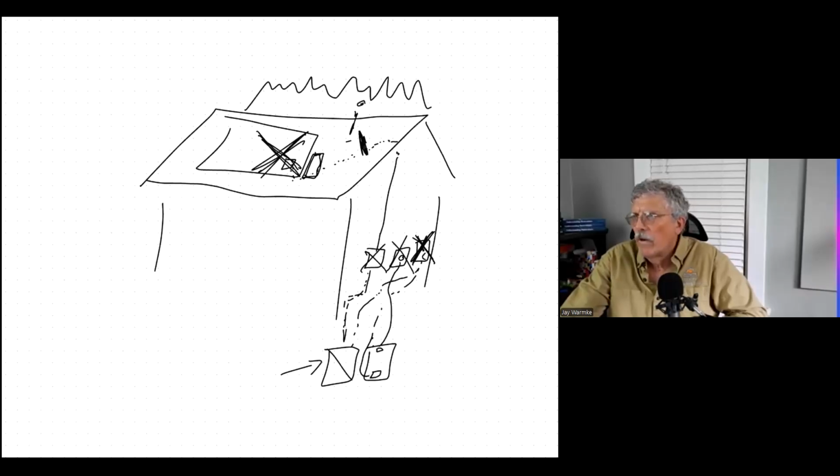They said like within 1 foot. So that was all fine. But that didn't work in residential. So then another company came up with the idea saying, how about instead of having one big inverter, why don't we make a bunch of little micro inverters and we'll attach one to each of the panels. And then when it loses sight of the grid, it's just going to shut off automatically at the array. And we'll meet that rapid shutdown provision.